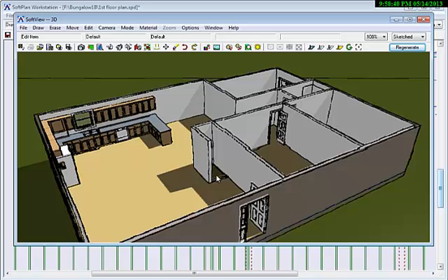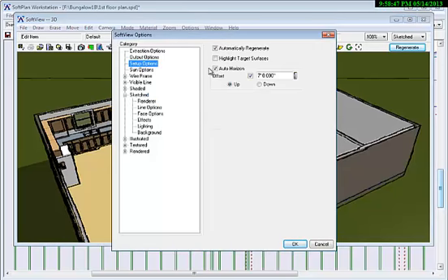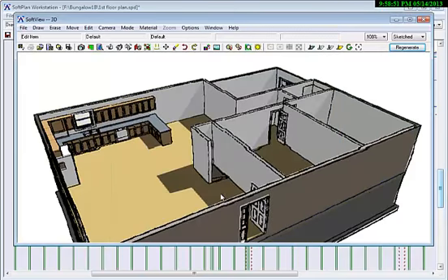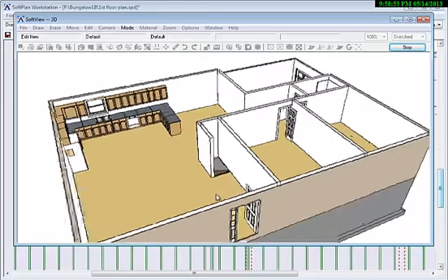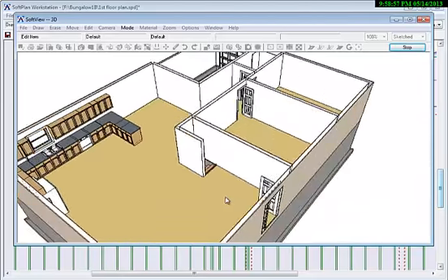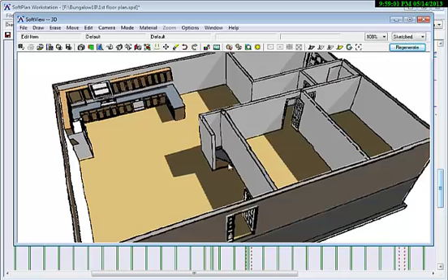We can't see fully through because we've got the horizon on. If you want to turn off the horizon for a moment, go to Setup Options, click on Auto Horizon, and now you can see that we're going right down into the basement with the stairs. There's lots of things that you can do down here. Add in a wall so that this doesn't look like it's wide open, or we can put in a railing to go down the stairs and so on. You'd want to do that kind of thing if you're designing this for real.